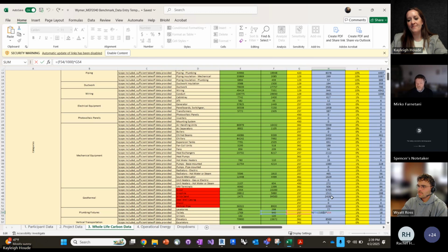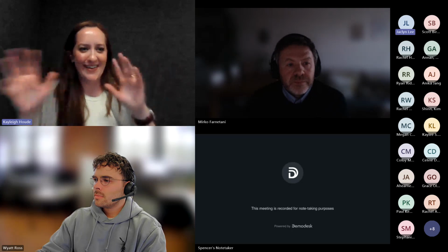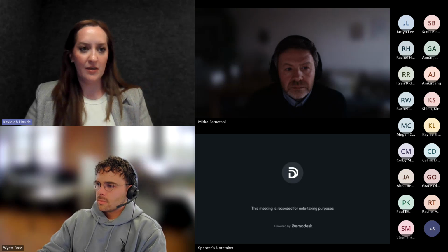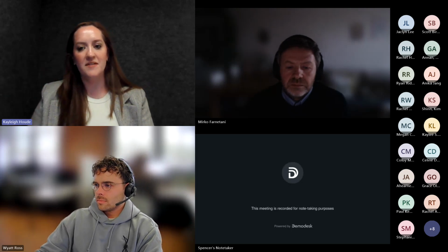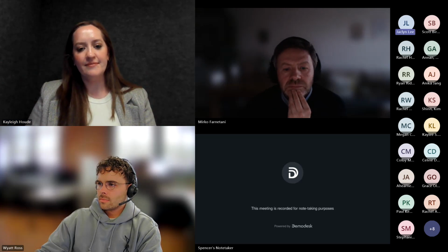Is there somewhere in this that we can make comments to ourselves, like it was 28 toilets, or would that be redundant since we have our other? Yeah, you can always do that as you're going along, just so that you have notes on what the category is. If you add a column in there, it won't mess it up. If you add it between these two columns, that would be totally fine. It shouldn't mess up any of the calculations. I've been doing a lot of that kind of tweaking back and forth, and it seems like it's fine. But yeah, I'd suggest making notes to yourself as you go along, to get all the quantity takeoffs, especially since we're between architecture and MEP now. Okay. Thank you.